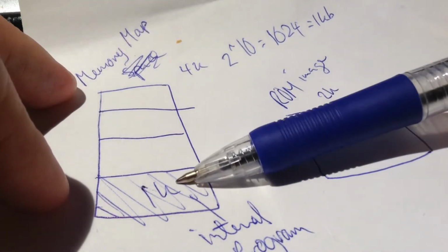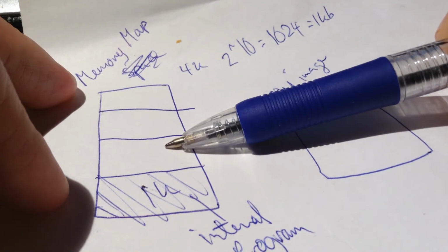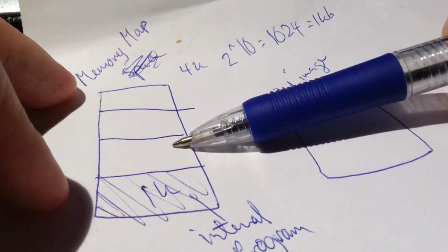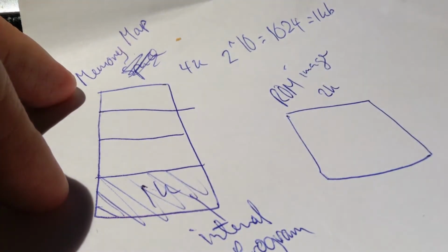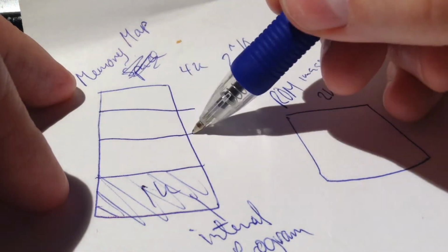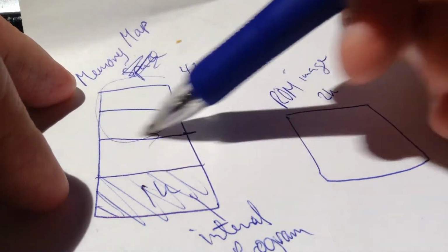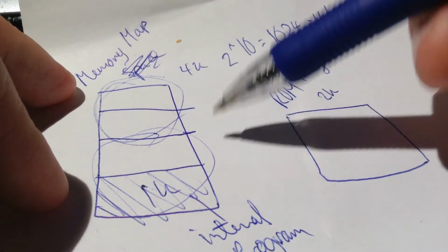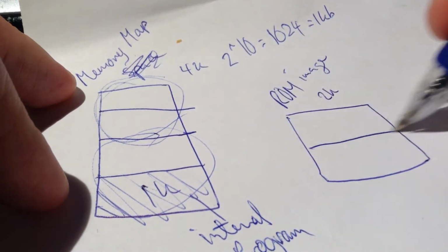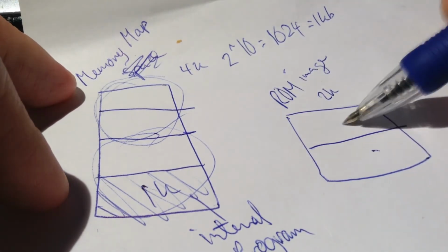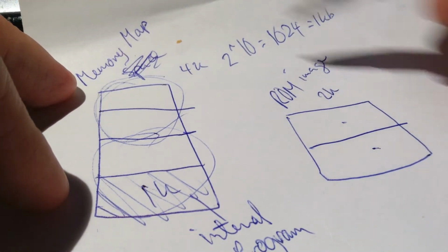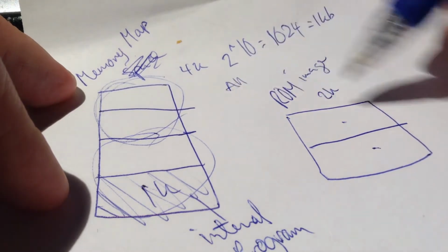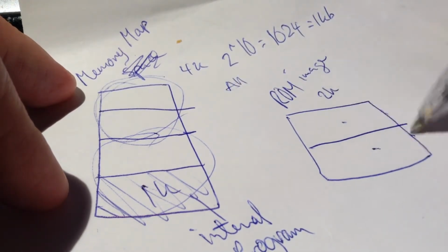That means if you are here or here, doesn't matter. You're still reading the same data because it's not connected, right? So what they do is that they use the next address line, which is supposed to jump from this area to this area. But instead it's used to jump from this area to this area in the ROM, because the A11 is now the one flipping the 1K.